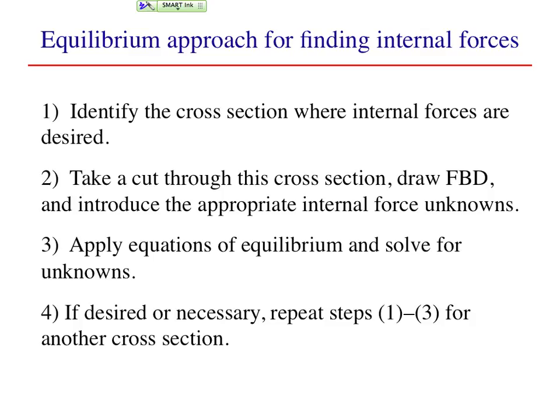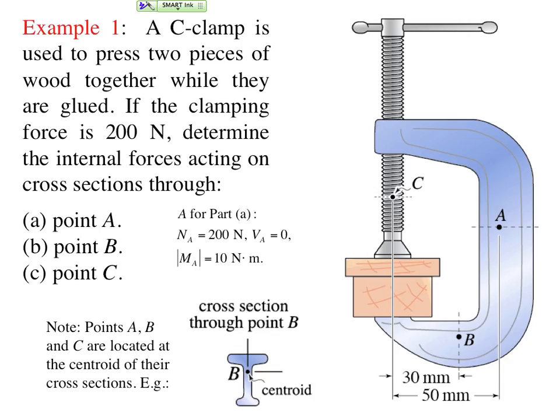Our approach for establishing equilibrium is no different from what we've done previously with whole rigid bodies. We now have to choose an isolating surface that passes through the rigid body, draw the appropriate free body diagram, and, if possible, solve for the unknown internal forces. We'll take a look at how to do this with 3 example problems.